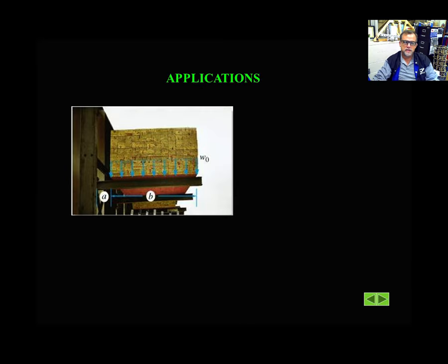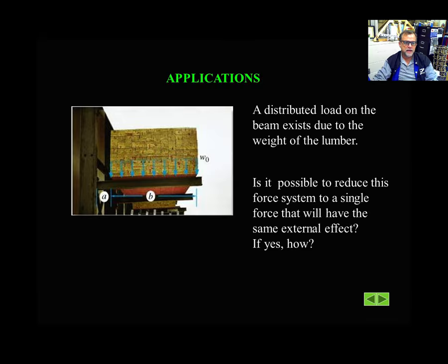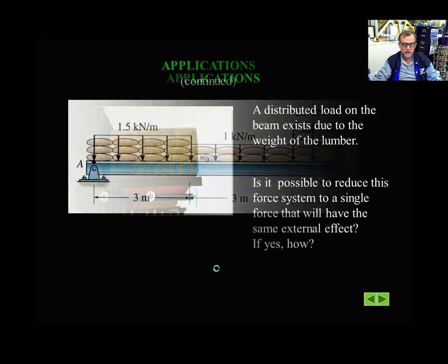And those are equivalent systems also: a distributed load converted into a single concentrated load. What is the reason for doing that? Well, again, externally, from the point of view of reactions, the effect is the same. Internally, or whenever you do shear and moment diagrams, which is going to be chapter 7, you do not do that. You do that only for calculating external reactions, and that's it. But when you calculate internal forces, forget about doing that, because then it doesn't have any correlation.